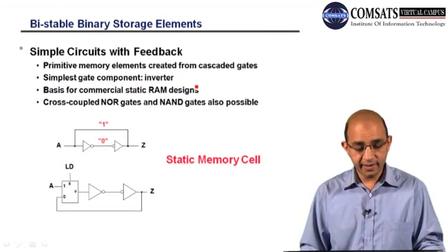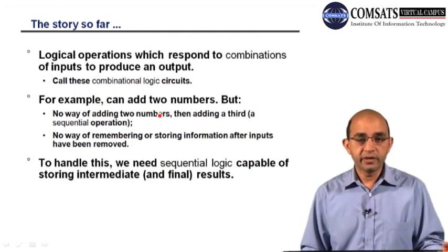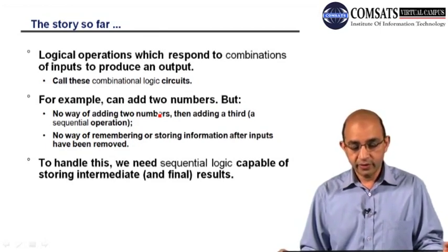And the gates are cascaded, and we have used inverters over here. And this is the basic building block for static RAM. So we have learned something new so far. The logical operations respond to combinations of inputs to produce an output. So as long as we have the input present there, we will be getting the output.